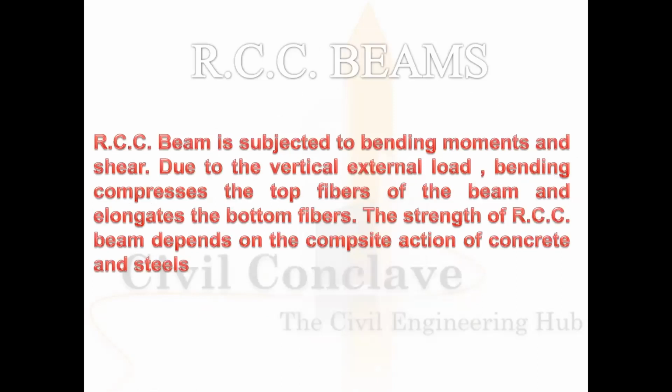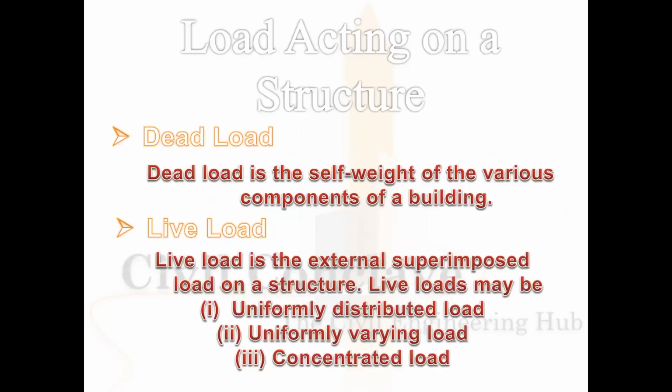RCC beams. These are subjected to bending moments and shear. Due to the vertical external load, bending compresses the top fibers of the beam and elongates the bottom fibers. That means the reinforcement. The strength of the RCC beam depends upon the composite action of the concrete and steel.